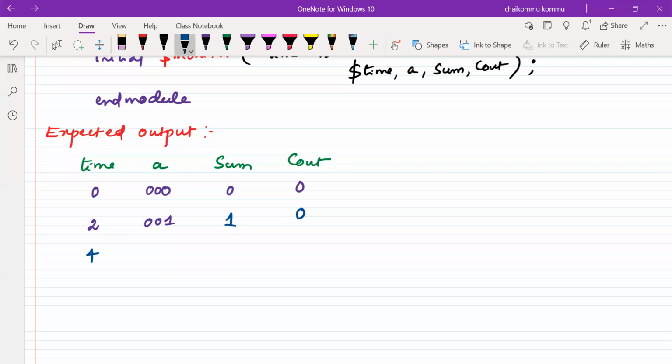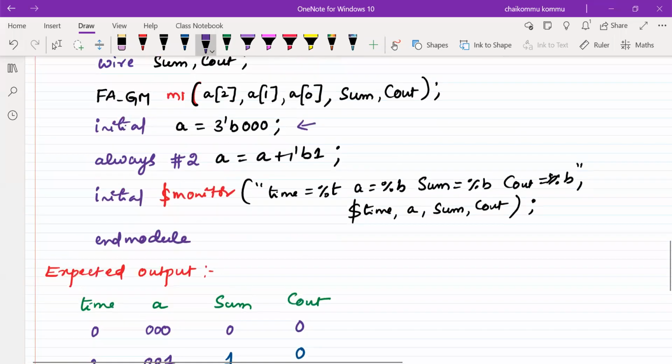So what is the value of this one? This value is equal to 0, 1, 0 added. So now the last bit is connected to C, this is connected to B, this is connected to A. Therefore again this is applied on a circuit, and it will produce sum equal to 1, carry equal to 0. That's how it produces. I hope you can understand this concept.